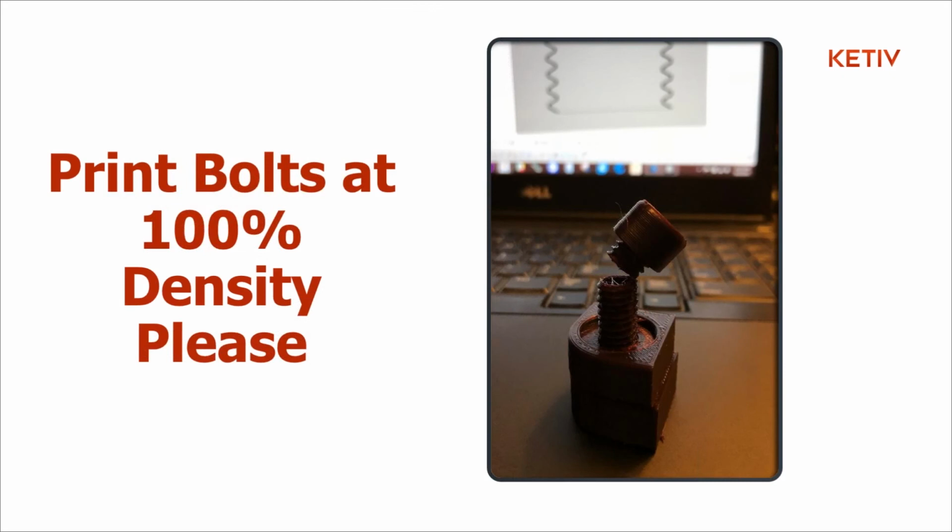Third tip: print bolts at 100% density, please. I tried this one at 15%. I already knew it was going to mess up, but I needed to show you guys that if it's hollow on the inside and you add a little bit more torque than it can handle, then it'll snap off. All the bolts that I print at 100% density are still intact. I applied a ton of torque to them, and they still haven't broken. So that's a good tip.